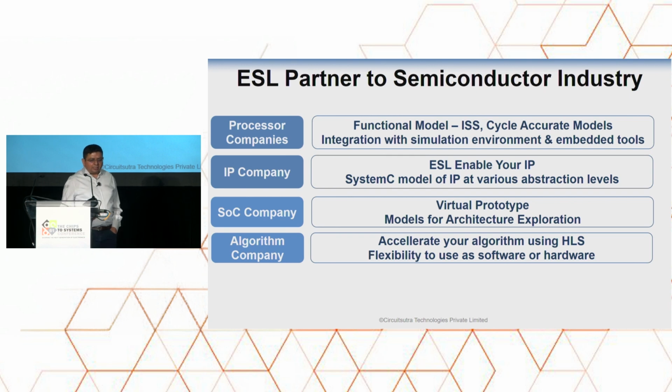So we have the right kind of expertise in these shift left methodologies, and we are uniquely placed to work with all the players in the semiconductor ecosystem. For processor companies, we can develop functional models or instruction set simulators and integrate them with various simulation environments or embedded tools, or even develop cycle accurate models of their processors, which can be used for architecture exploration, etc. For IP companies, we can enable your IPs with these advanced shift left methodologies by developing SystemC models of your IPs and protocols at different abstraction levels.